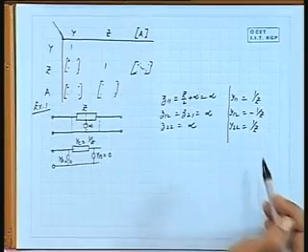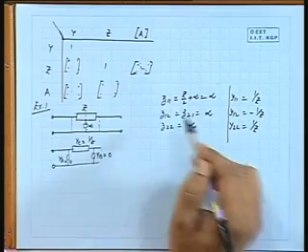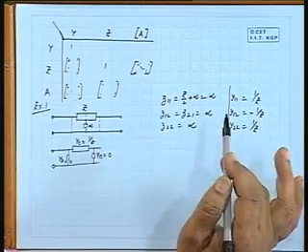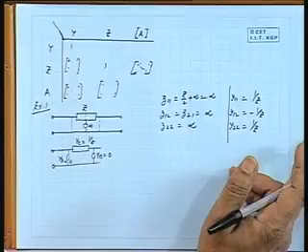All right. This is something very interesting. The Y matrix parameters are all finite, whereas the Z parameters are all infinite. There is no finite Z matrix, whereas there is a finite Y matrix. What does it mean? Z is the inverse of this, so the inverse does not exist. It is going to give you a singular matrix. Let us see.